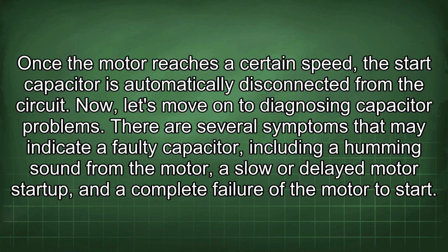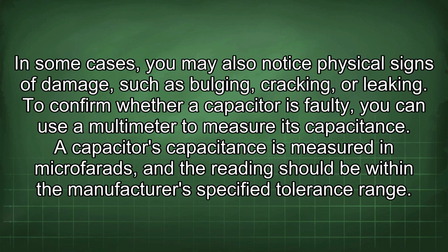Now let's move on to diagnosing capacitor problems. There are several symptoms that may indicate a faulty capacitor, including a humming sound from the motor, a slow or delayed motor startup, and a complete failure of the motor to start. In some cases, you may also notice physical signs of damage, such as bulging, cracking, or leaking.